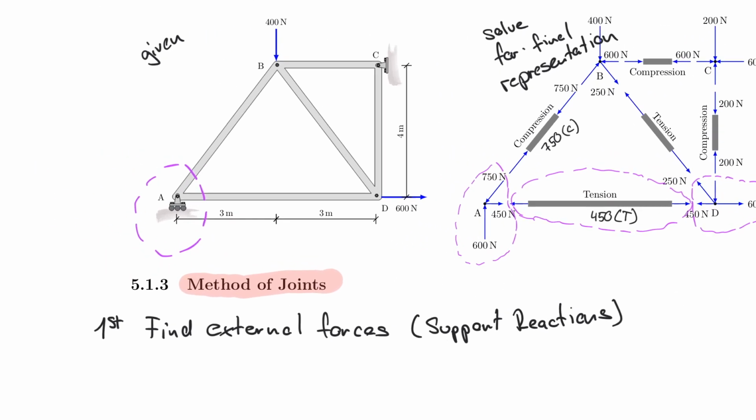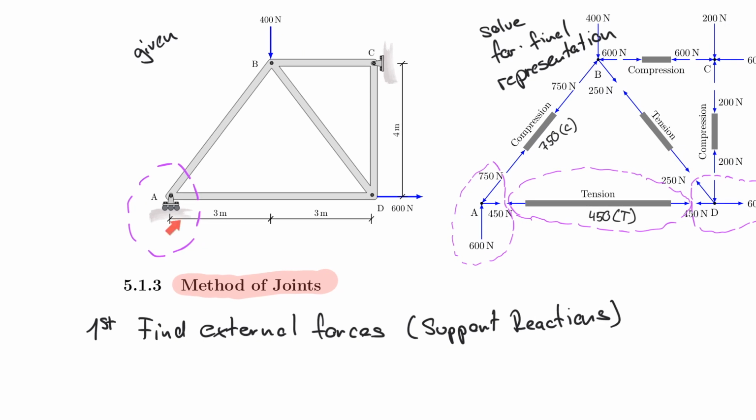So let's take a look at the structure here. If I cut node A, if I release joint A, then I release 1, 2 member forces. If I cut through node C, I release this one, and I have 2 unknown forces if I have my support reactions. However, if I release node B, then I cut through 1, 2, 3, and I cannot solve that because I have 2 equations with 3 unknowns. Impossible. Same is true here at node D, so I cut through 1, 2, 3. I could not solve this.